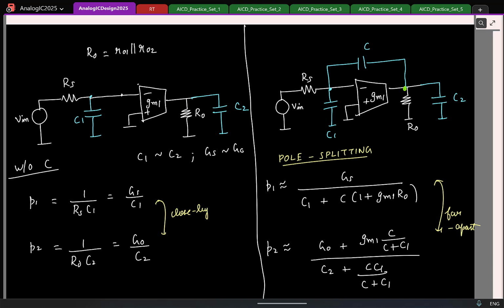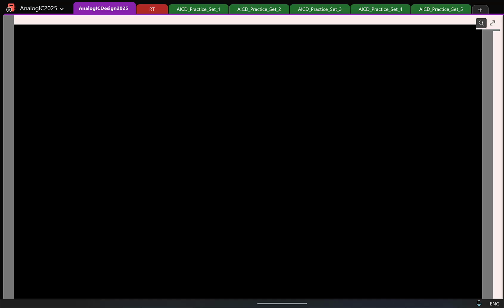Okay, so now remember that we looked at the common source, right? And I only looked at the small signal picture, and I'm sure you know that I cannot, or first let me ask you, can I connect the small signal directly to the gate of the transistor and expect the transistor to work? So what should I do? Should bias it. So let us say I have a small signal voltage source, and let us say DC bias VB. How do you connect the two now?